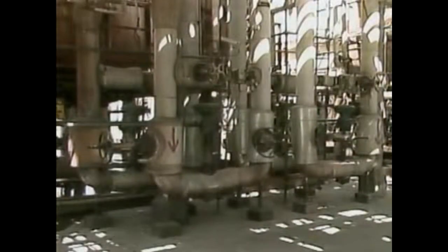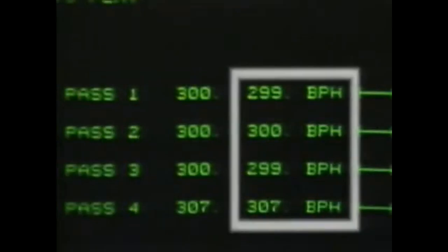Besides temperature, the process fluid flow rate is also monitored. The fluid has to flow at the proper rate to be heated to the proper temperature. The flow rate for process liquids is often measured in barrels per hour. For many furnaces, both the process fluid outlet temperature and the process fluid flow rate are controlled automatically. You should know how your furnace's control systems work so you can monitor the way they're controlling the furnace.